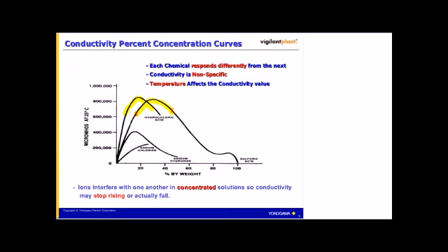Now, the simplest solution to this problem would be to make sure that the range you set up never crosses that peak point. However, there may be occasions where that's not possible. So what do you do then? Well, it becomes a little more difficult, but using two analyzers and a secondary device such as a flow meter to validate which side of the curve you're on, and a way to switch the output from the first analyzer to the second one once the peak is reached is a way of doing this.